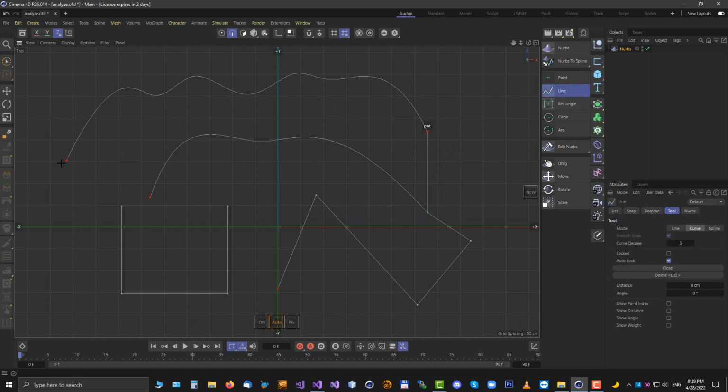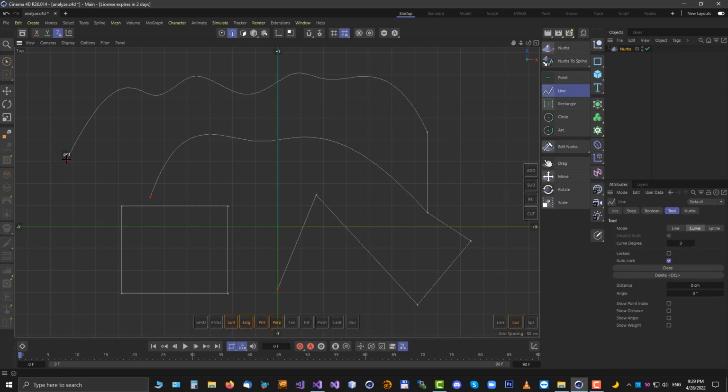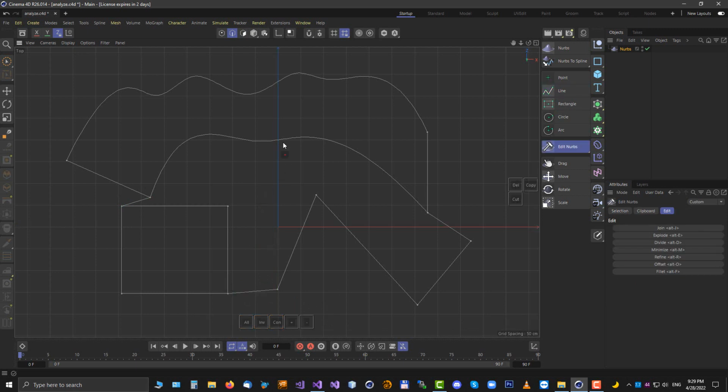So if I quickly now add this line and remove these loop disconnections, then I will change this floor plan, or shape of the curves, into loops without disconnections, and now you can safely convert it into polygons.